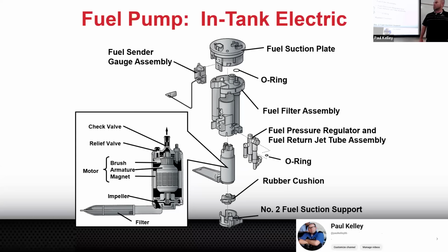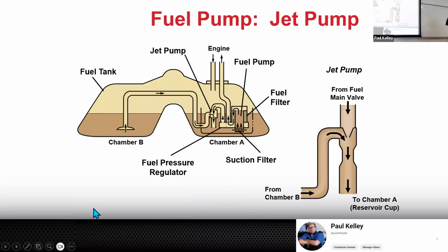If you have a bunch of garbage in the sock, sometimes shaking it and having a little bit of stuff pop off of it, it'll fire up. But then when it starts sucking fuel up, it'll reclog it. That's true too. So then it'd be like, well, let's try to add a few gallons. And if with a few gallons it still does the same thing, no, we're going to have to pull the pump. And then when you pull the pump, we'll show this next page, you're probably going to end up having to do a full fuel tank clean.